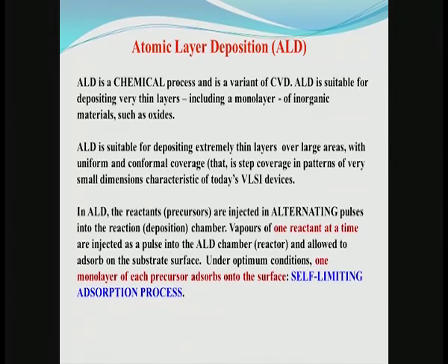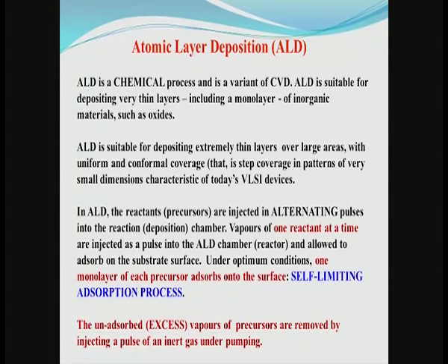In ALD, reactants are injected in alternating pulses into the reaction chamber, and vapors of one reactant at a time are injected in as a pulse and allowed to adsorb on the substrate surface. Under optimum conditions, one monolayer of each precursor adsorbs onto the surface, resulting in a self-limiting adsorption process. It depends on a self-limiting adsorption process. The unadsorbed or excess vapors, because we only require a monolayer, are removed by injecting a pulse of inert gas